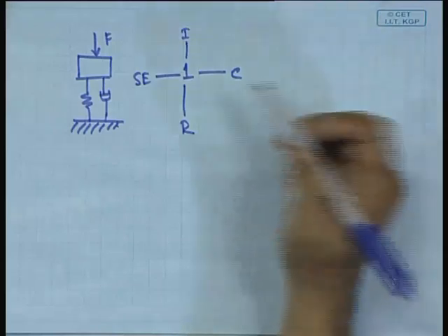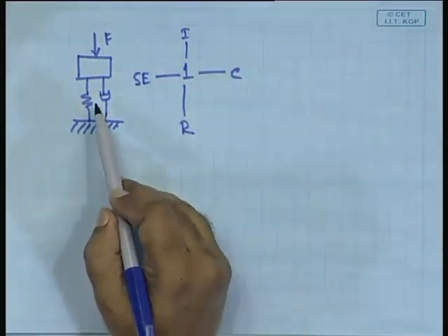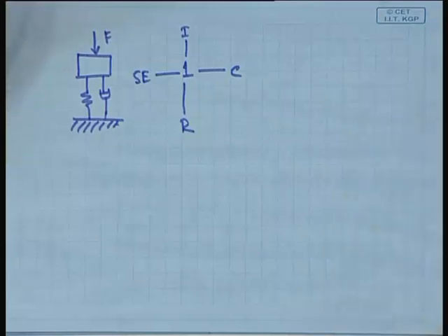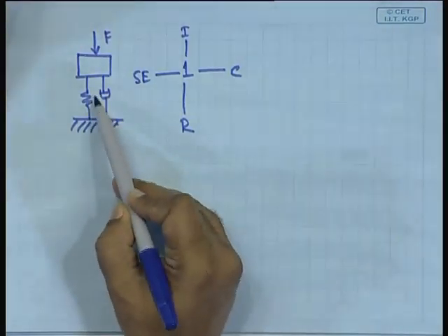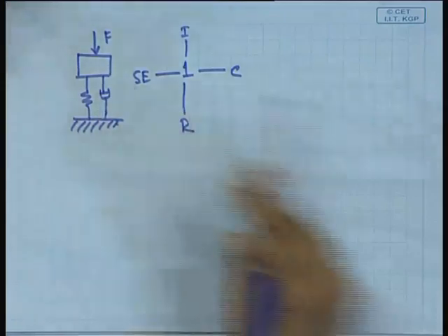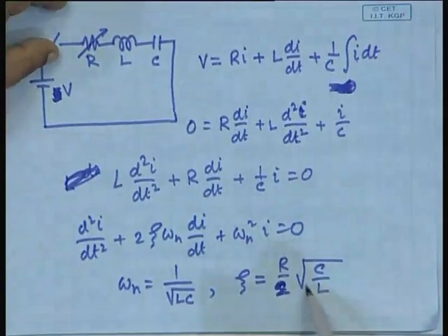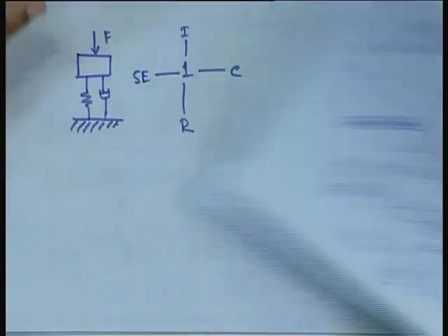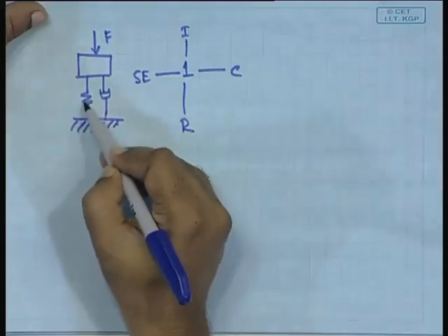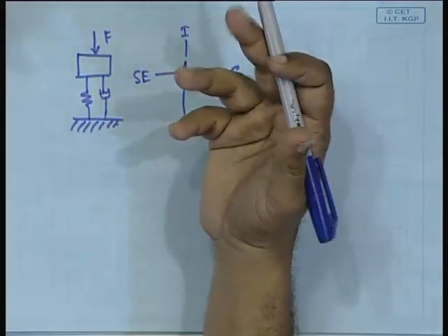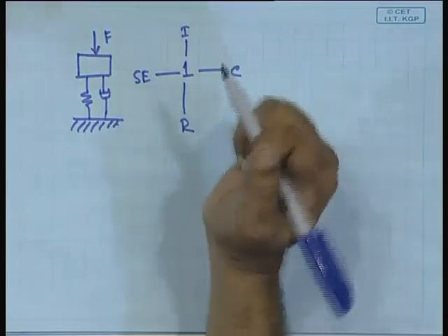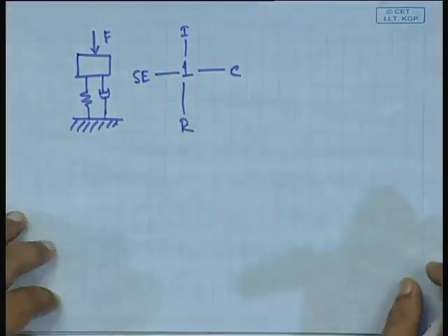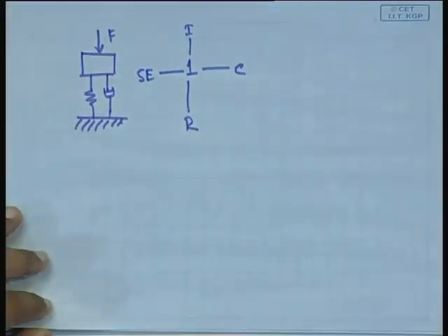Fine. So, this kind of system's behavior will also be determined by the same kind of dynamics, and depending on the value of the damping, it will either be underdamped or overdamped. Not only on the value of the damping, remember it also depends on this term. So, if you keep the R constant and vary this, that means you slowly increase this spring constant, then also it will exhibit the same kind of behavior. Clear? Okay. Yes, I knew that you have done the time constant business earlier, but nevertheless it was necessary to place it in a general format.